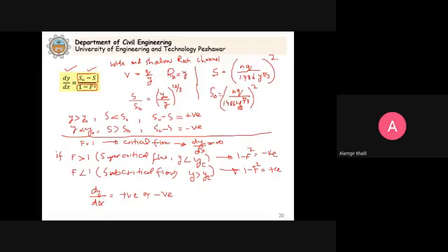You will determine the overall sign of the numerator and the denominator, and then it will give us the resultant sign for dy by dx. If it is positive, the depth is increasing. If negative, the depth is decreasing along the channel.